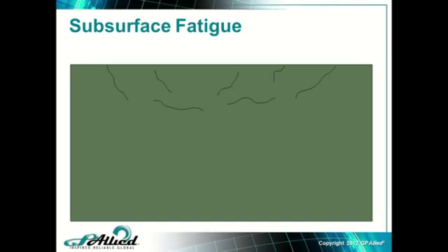Every time, you can imagine, every time a roller passes here, we get compression and we get relative movement inside the crack. So every time we have small motions under high stress, the frequency will always be high. If we had large motions under low stress, then it would be very low frequency. But we don't have that. It's very high stress. Nothing has broken loose yet.